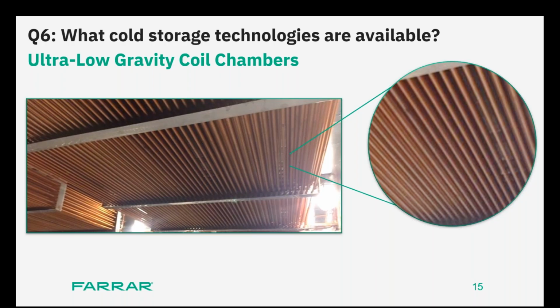Because when you do a defrost on the systems, you do have to remove all the product, and you do have to warm the ultra lows up, the minus 20s up, and generally they'll turn the 5 degrees C cold room vestibule off as well, just so that you can get any form of moisture that has occurred on it cleaned up, picked up, and out of there, then bring the chambers back down into proper operation again. So it's the most common solution that's out there right now that's been seen, but there's also a few other ways that can be done, and it's really exciting.